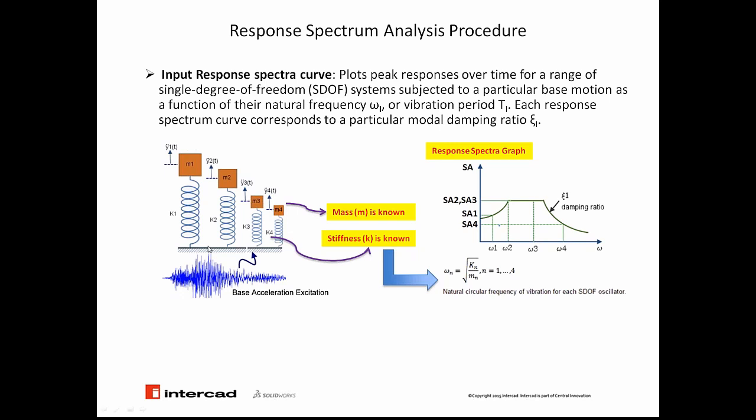Then under such loading, with the known values of m and k, we measure the response, and that is the y-axis. So if you have the response spectra graph, meaning the peak response of the structure to a dynamic loading, then in response spectrum analysis, we enter such a curve into the analysis and combine the effect of these peaks with different methods, and look at the maximum response of a structure while such loading is applied to the structure.